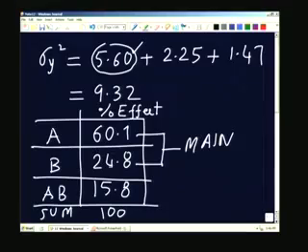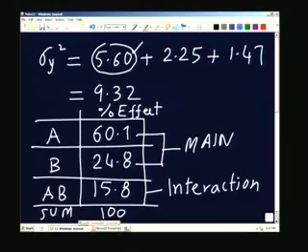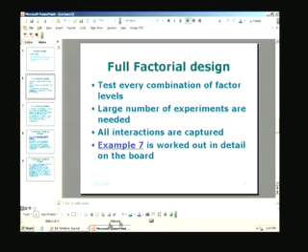Main effects are 60 plus 24, 84.8%, and the interaction effect is about 15%. So, this is not necessarily ignorable or negligible in this particular case. Therefore, in this particular experiment or process, the speed, the depth of cut and the product of these two are all playing a significant role. However, the relative significance of each is determined by the relative magnitudes of the variances due to each one of these, and that is what we have tried to do there.